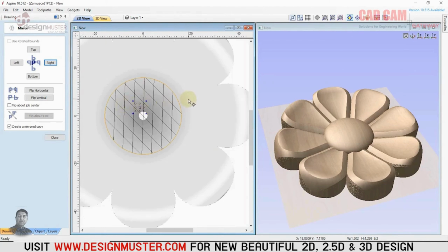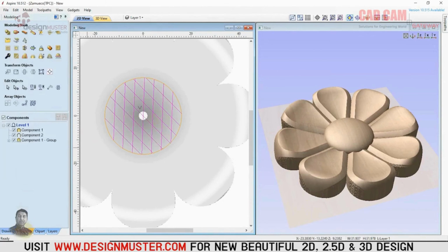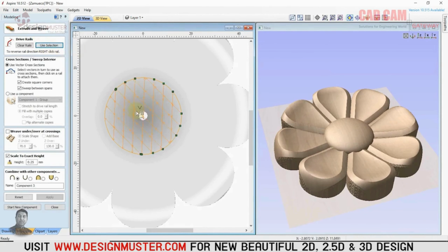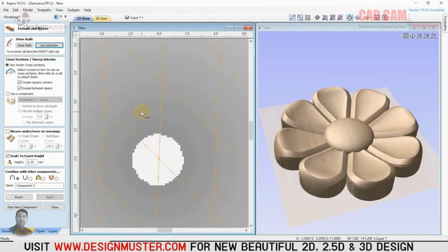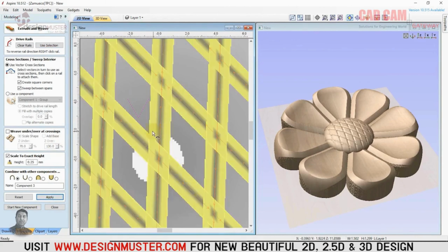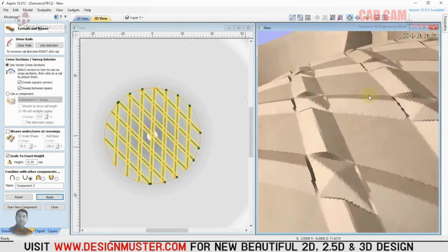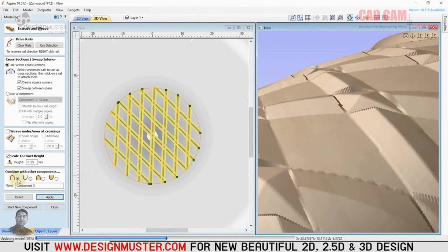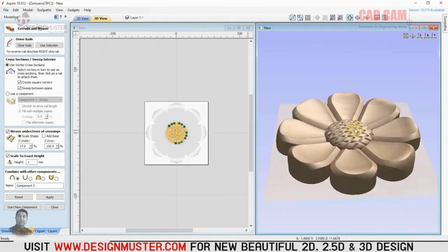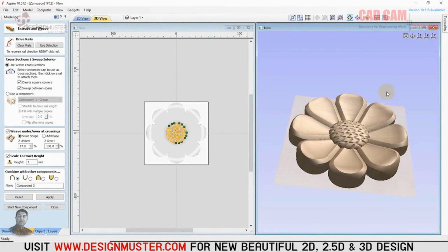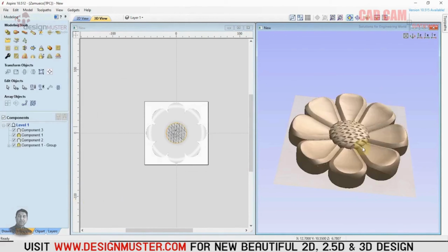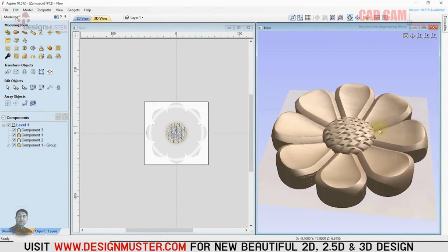After that, close it. You have selected this object. Now go to modeling. Here we have the command create a shape by extruding along one or more center lines. So here, all these center lines are already selected. Use selection. This is my one selection. Select this one and apply it here. As soon as I applied it here, you can see the design. Now, since we made it in the opposite direction, you'll need to take this position, so it will be created on the inside. God willing, we'll keep discussing what more we can do with this, and which additional features we can apply to it. We'll keep learning new commands along the way.